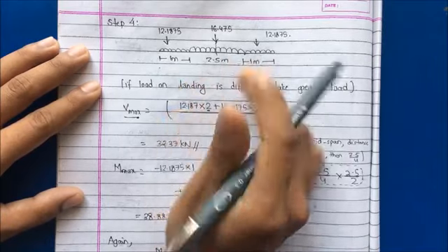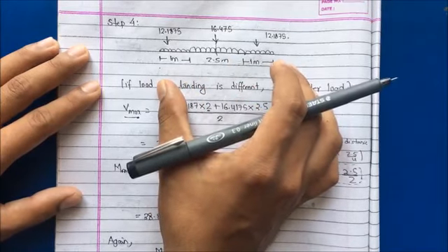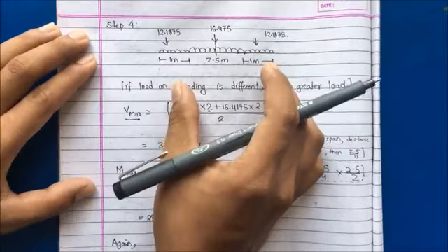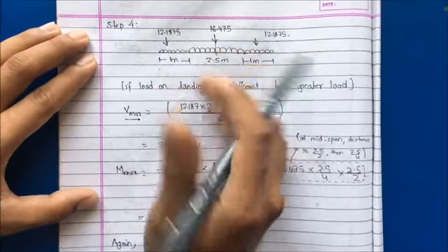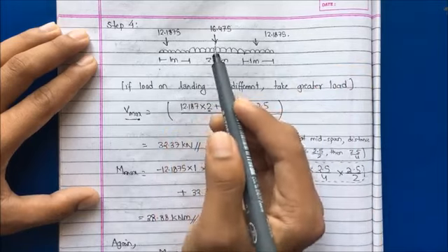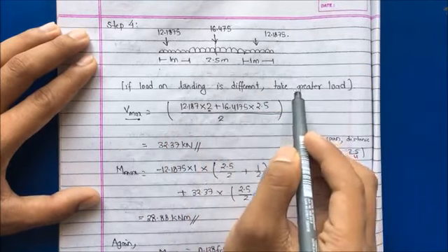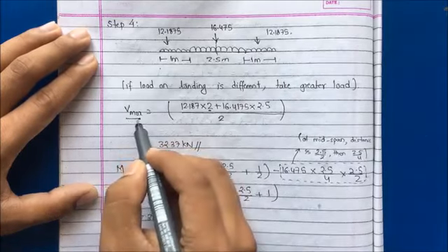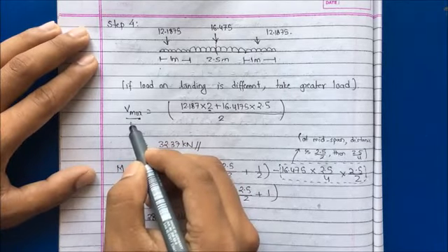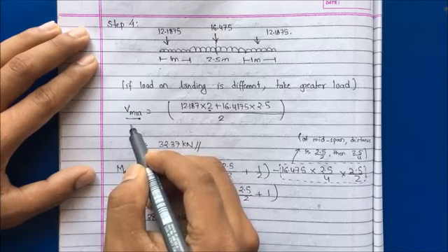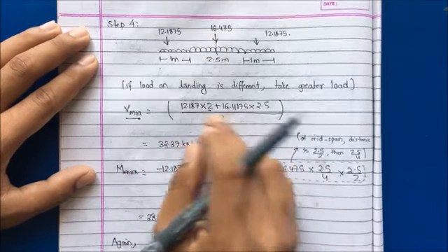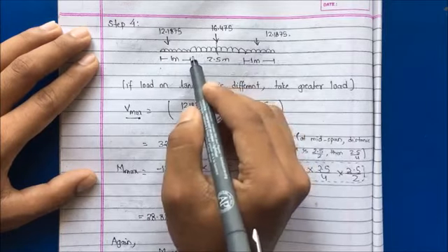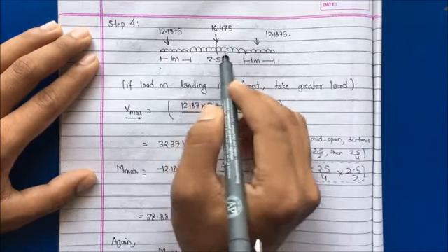Okay, the load acting on the landing portion is 12.1875 and 16.475 in the going. Sometimes the load acting on the landings may be different. So in that case the load which is greater on landing is to be taken for the calculation of shear force. Now Vmax, this is the maximum shear force, and for maximum shear force we have the formula W into L by 2. For the shear force, we will take the sum of shear force acting on landing as well as the going portion.